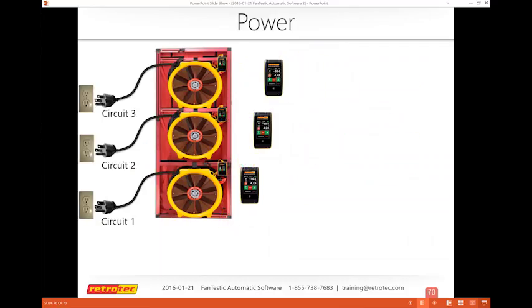The last one I'll touch base on is to make sure you have enough power for what you're going to do. Some people may decide that they need 4 fans to do a multi-fan test, but realize that there's hardly any power in the lobby or anywhere near there. Many of these fans really should have their own entire circuit; 2 of them are going to blow a 20 amp circuit. That's common for most any fan you would use. So you need to make sure that you have the right amount of circuits, know where the breakers are, have access to them, and if you're going to use extension cords, that they're also rated for the right size.